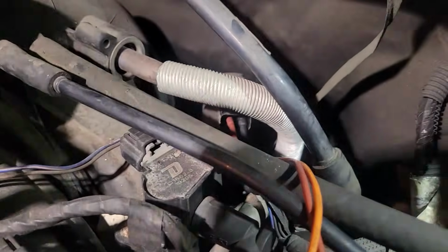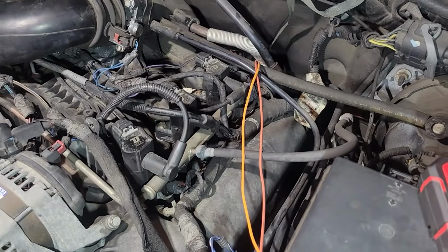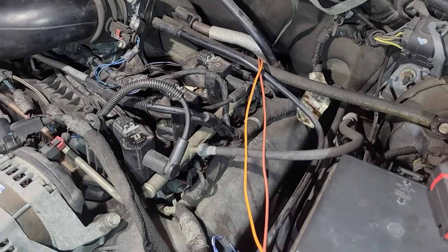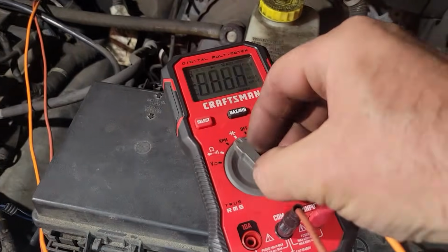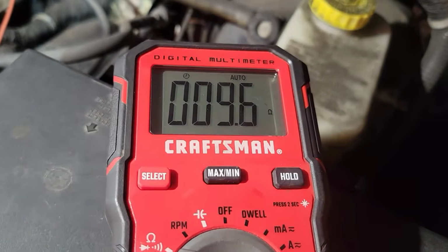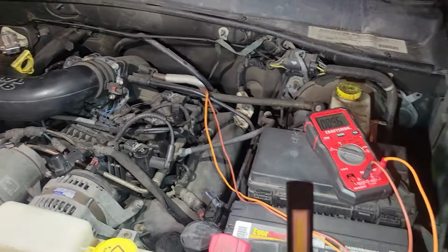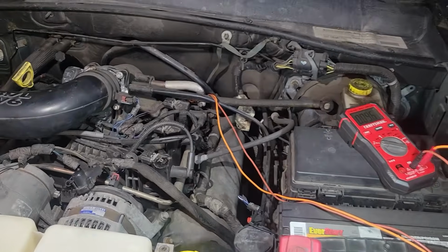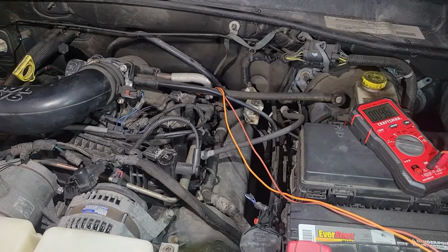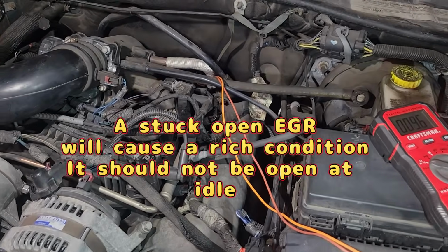I made these leads a while ago. It's good to keep them in your toolbox and use them again. I know several different sizes, but the spec should be between 9.5 and 10.5 ohms. 9.6, we're right in there, on the low end of resistance, so that's good. Good low-tech test. Just put your mind at ease, because whenever the valve sticks open, it usually causes a higher resistance. So I always double-check these things.